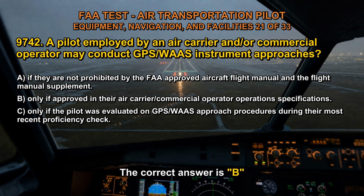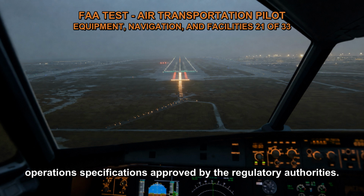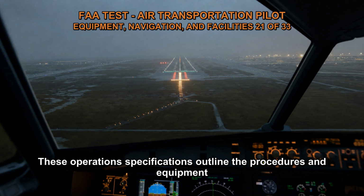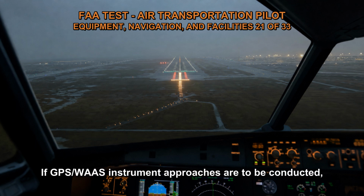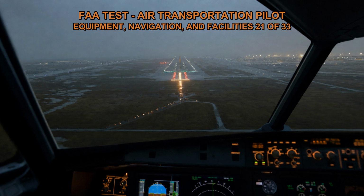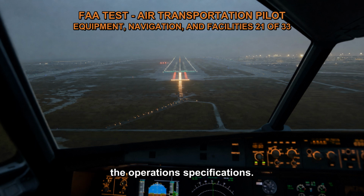The correct answer is B. Air carriers and commercial operators operate under specific operation specifications approved by the regulatory authorities. These operation specifications outline the procedures and equipment that the pilots are authorized to use. If GPS/WAAS instrument approaches are to be conducted, it must be specifically approved and documented in the operation specifications.